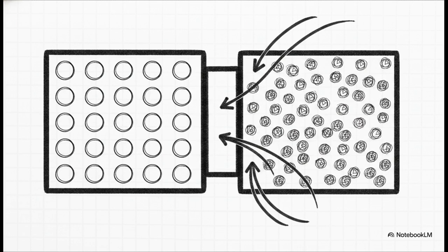But as they move, they leave behind the stationary atomic nuclei of their dopants. These are charged ions locked into the crystal lattice. This mass migration creates a central depletion region right at the boundary. It's essentially a no man's land, completely stripped of free charge carriers.